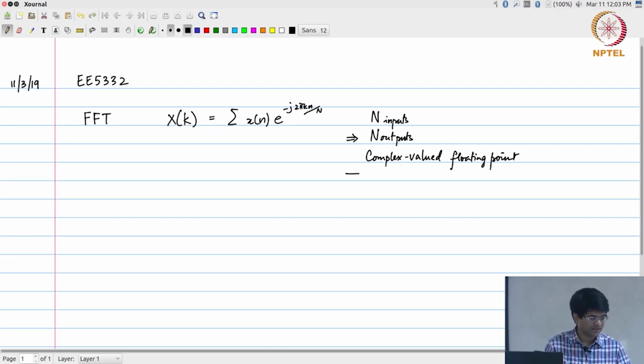As part of assignment 3, we also went through the process of converting this into the AP fixed format, where you essentially had to use some fixed point representation, a finite number of bits with some bits reserved for the integer portion and the other bits reserved for the fractional portion. Okay, so all of these steps are already completed.